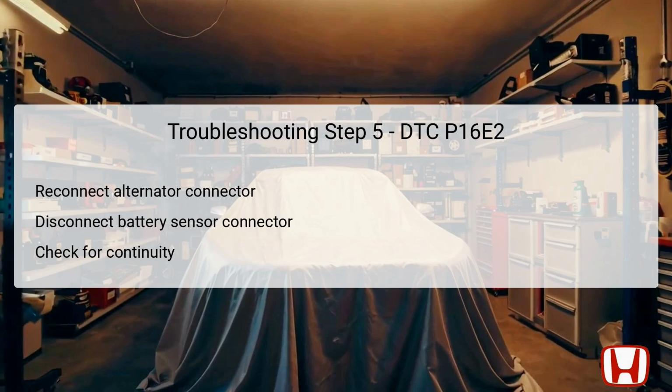A finding of continuity in this test indicates that the alternator is at fault and should be replaced to restore communication between the systems. If no continuity is found, however, continue to Step 6 for more diagnostic measures.